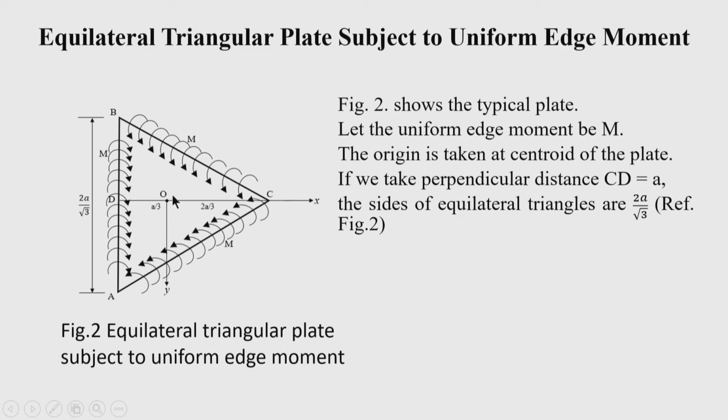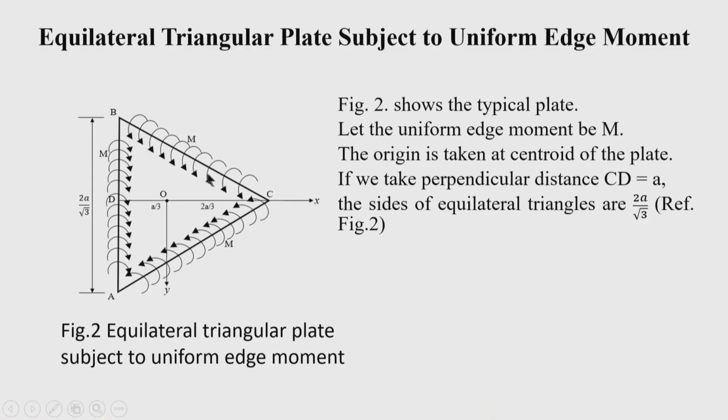So, after getting the CG, now let us formulate the problem. So, we can see that at the boundary, since it is simply supported, again we are taking this plate edge as simply supported, because we are dealing with only the simply supported condition. So, in the simply supported case, along the boundary deflection is 0, that is obvious, and another condition is that bending moment is 0.